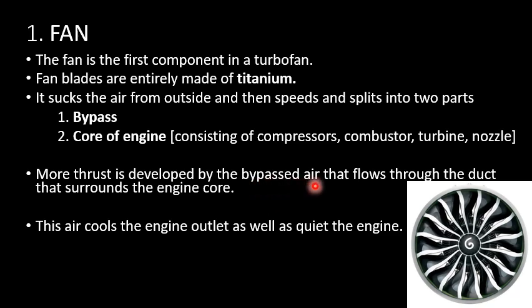That is the necessity of a bypassed region. And this air cools the engine outlet as well as quiets the engine. So the bypassed air can cool the engine outlet and reduce the failures of the engine, and also it can quiet the engine. That's the basic purpose of a fan.